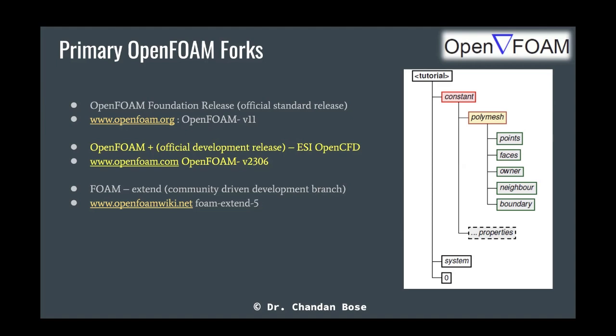Okay, taking them one by one, steady or transient, that's true, that will depend on your solver, so which solver you are choosing is one thing. But more basic things: for example, when do you want to start the simulation? When do you want to end the simulation? What will be your delta T of the simulation? You have to tell those information. What will be your time step while the simulation is running? Do you want to keep a fixed time step, or do you want to use an adaptive time step based on stability criteria such as the CFL number?